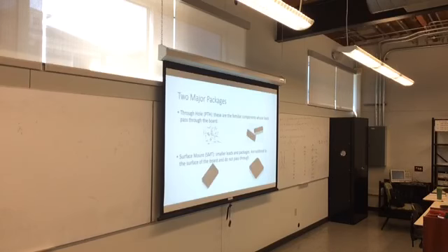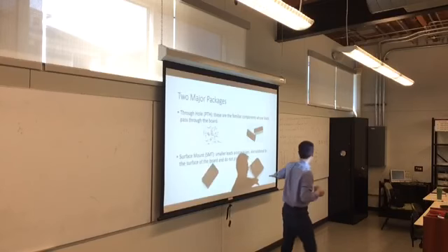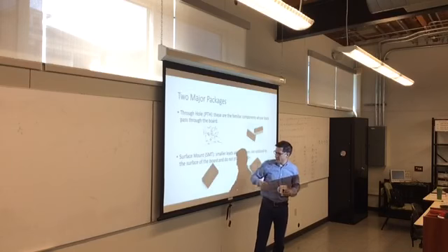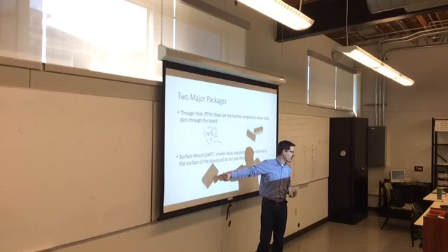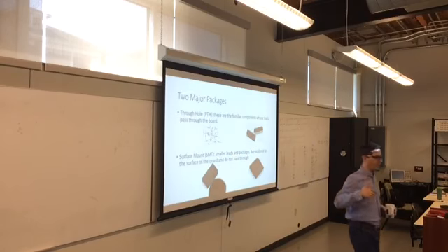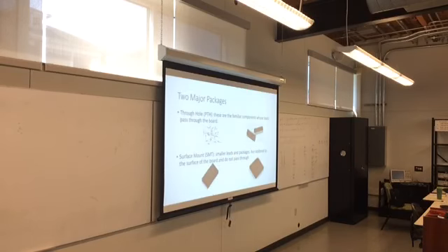Chips are manufactured in a variety of pin packages because some people want through-hole components like the ones on the right. Some people want surface mount components with little flanges on them for the pins. And some people don't want any leads or anything, and they're tucked away underneath the package. So a part may be manufactured in 3 or 4 different pin packages.